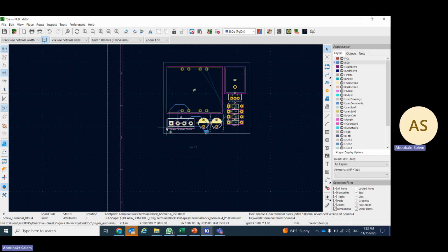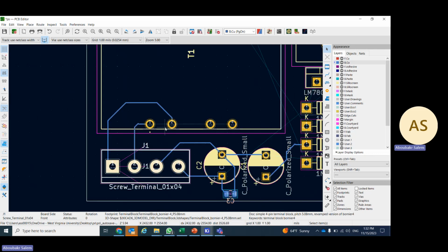So you have to keep a certain distance between tracks. My recommendation is you already have a certain distance between the terminals of the AC, correct? Keep this distance all the time, so without any calculation, I don't need to make calculations now. Since the designer already made these terminals with this distance, try to keep this distance between the tracks of the AC. So it's almost the same distance here between this line and this drill or via and these lines as well. Okay, guys?